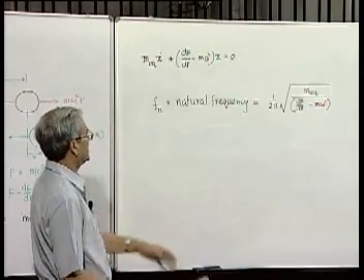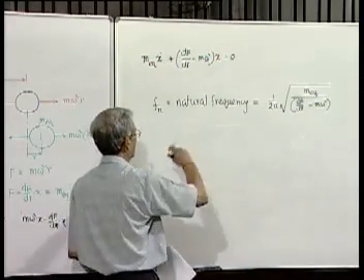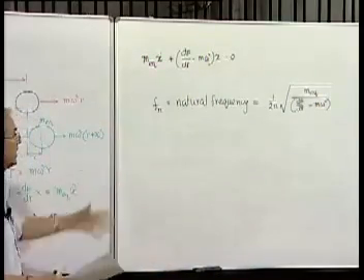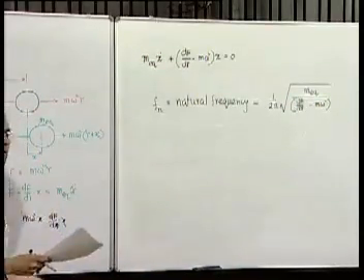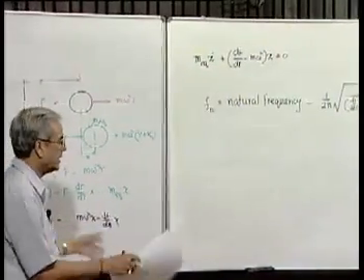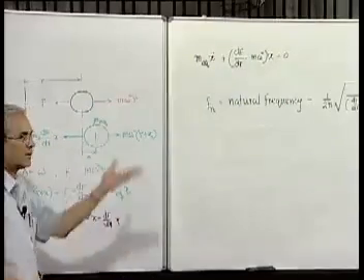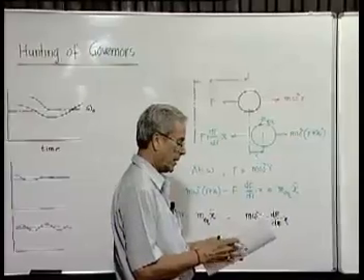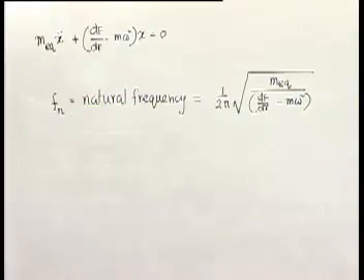So, once this frequency becomes very close to the frequency with which the load fluctuates, then the whole system will undergo a resonance. That means, the whole governor and the whole engine system will hunt or fluctuate in its speed and operation. I think this brings us to the end of our centrifugal governors, but you remember that we mentioned